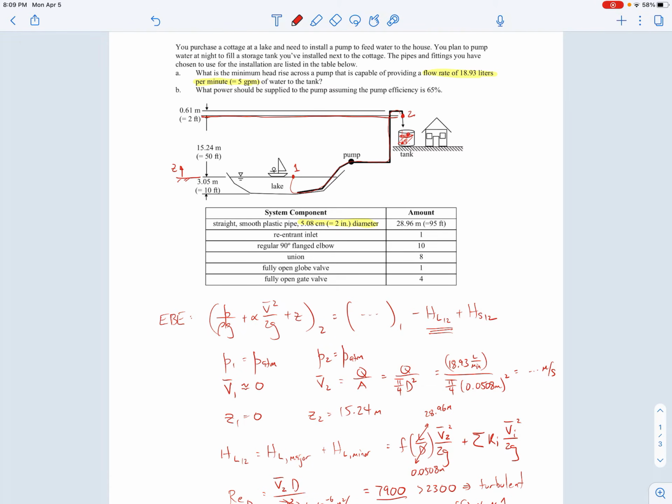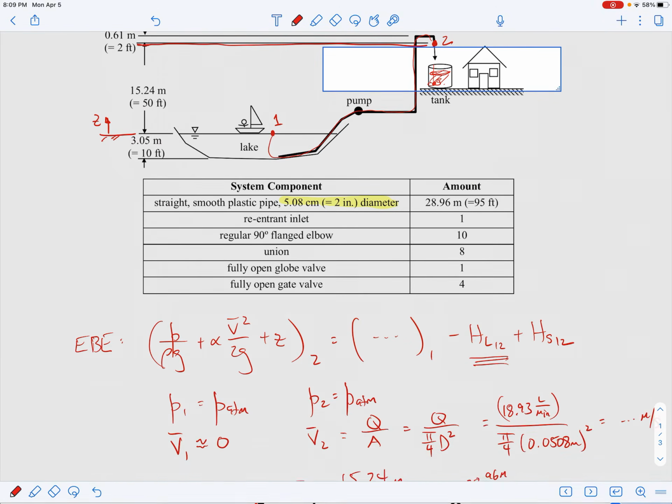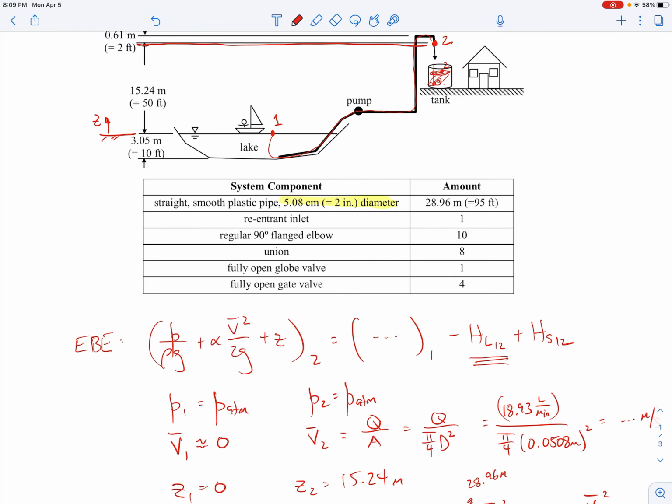And if we chose our 0.2 at the free surface of the tank, then we would have an exit loss of 1 because we would lose all the kinetic energy in the flow as it came out of the pipe and went to the free surface, because the velocity on the free surface is equal to 0. So all that kinetic energy coming out of the pipe would have been dissipated away. But because we chose our 0.2 up here, when the fluid velocity comes out of the pipe, it hasn't lost any kinetic energy. So there is no exit loss.